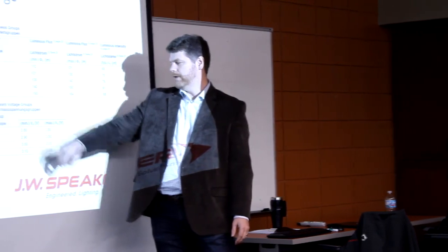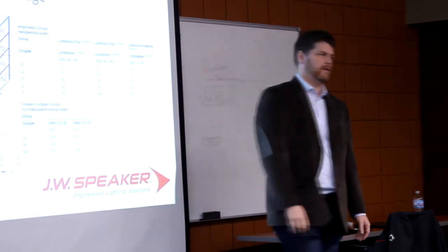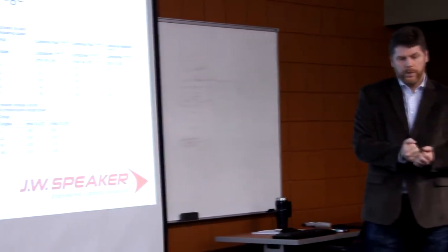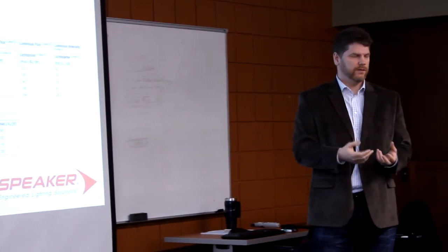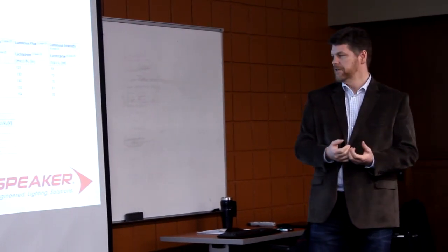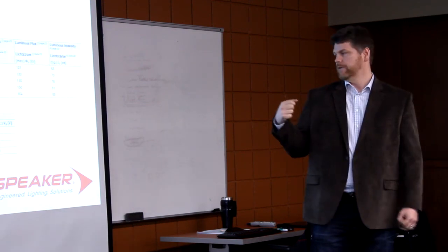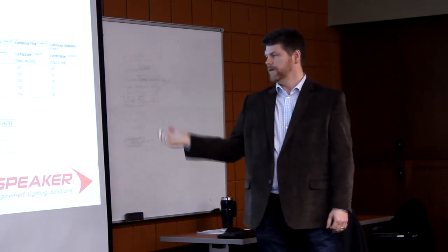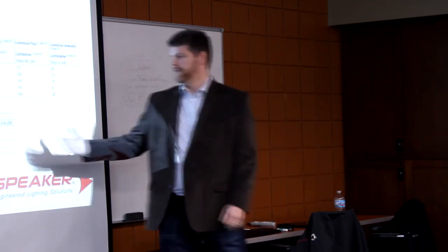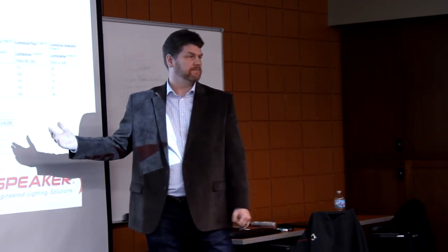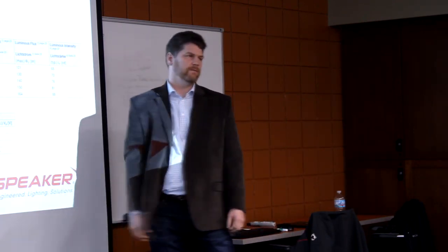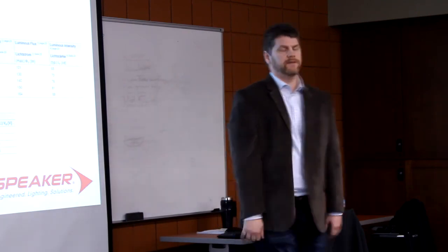It goes from 2.8 volts all the way to 3.25. We don't limit the binning as far as voltage because that would be very expensive and be another thing to take away. So we typically accept it all, but the electrical engineers, when they're designing the circuitry, have to account for the min and max voltage that the LED has.